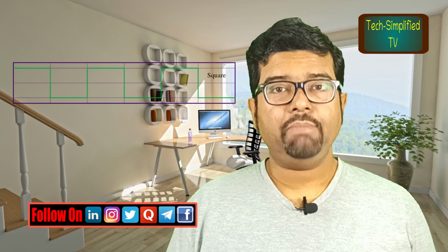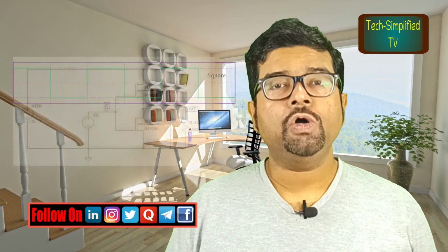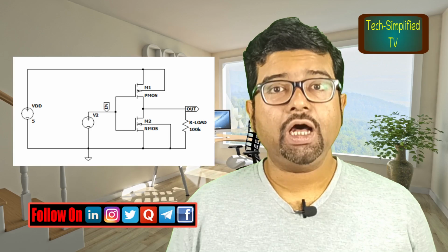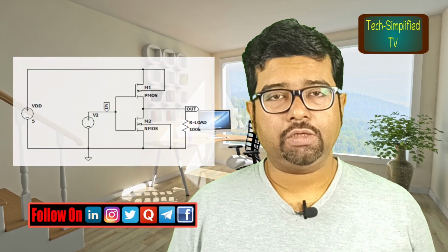We will apply a pulsed waveform shaped like a square waveform as the input to the constructed inverter. We will apply proper DC biasing voltage and transient analysis to check the functionality and performance of the CMOS inverter. So stay tuned, stay focused.